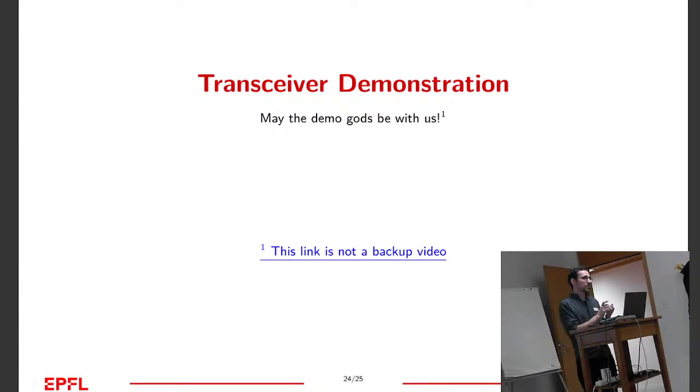Yeah, because you don't want to transmit for multiple seconds. The longer you transmit, the more energy it uses, and most of the applications I've seen are more interested in low battery consumption. So if you have a few kilobytes per second but you transmit for 1 millisecond, then it takes you a few bytes.